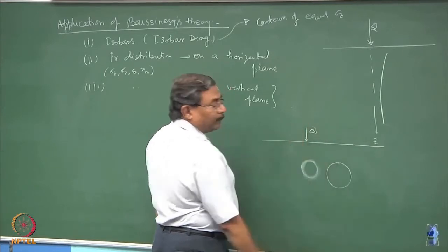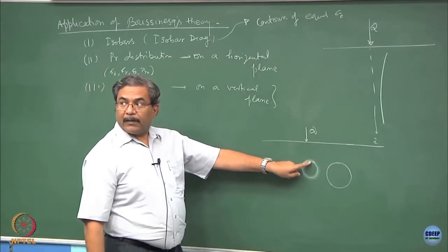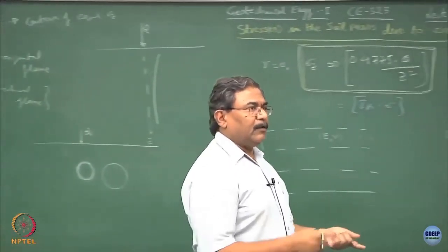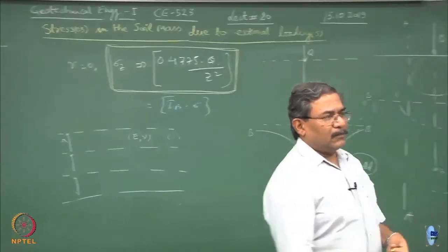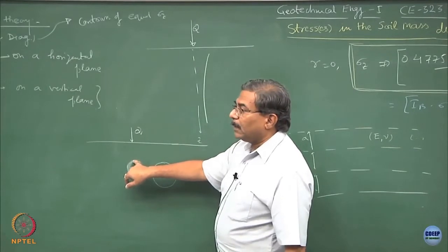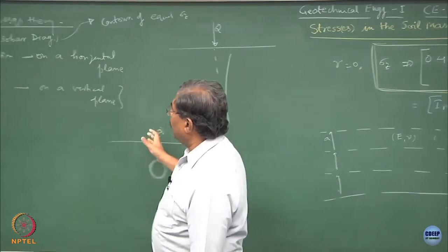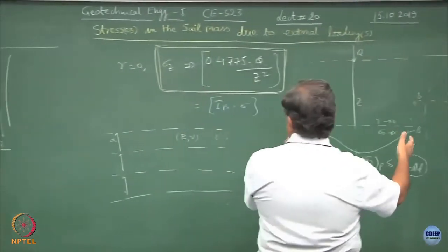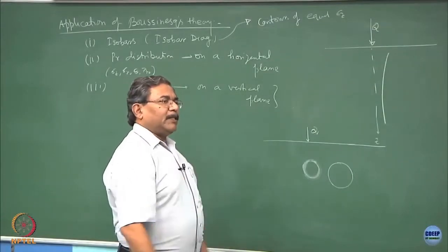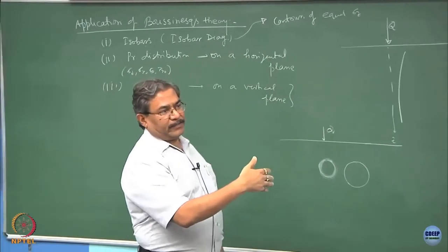If I know the value of Q, I can find out the state of stress at the crown of the pipe. Pipe is made up of some element, either a structural element, steel or mild steel, or concrete or whatever, and then I can compute the yield strength of the pipe, and then we can design it accordingly. Fine. This is another good example of where the application of these types of computations would be in real life. So, it is always the vertical stresses which are going to be much more detrimental as compared to in plane or perpendicular to the plane stresses.